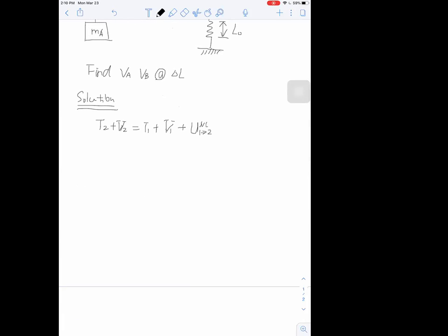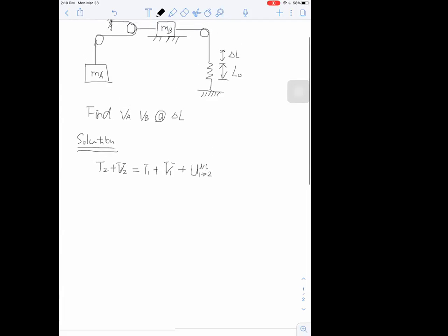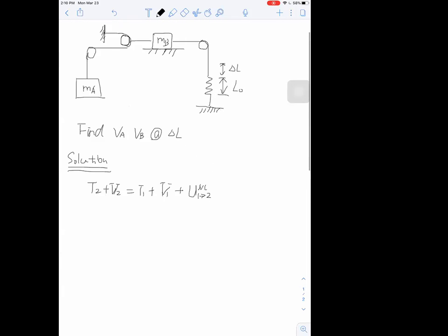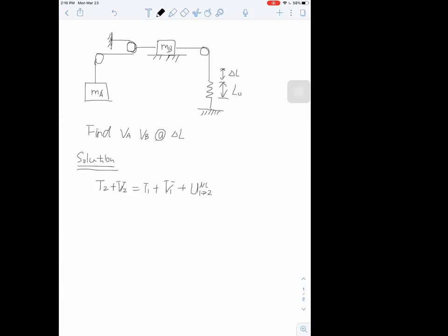And so during the 5 steps, 6 steps approach, I told you, you will need to write out all the kinetic energies for each mass, right, as step 3. And there's actually one trick I learned from Dr. Teicher, which is very good. It's to create a table for your kinetic energy for each mass.